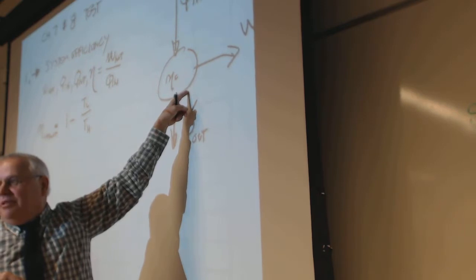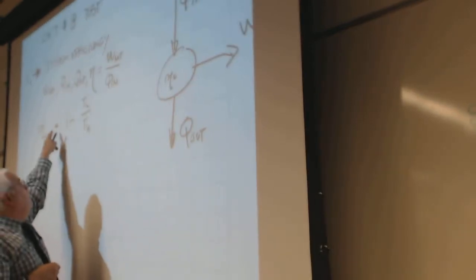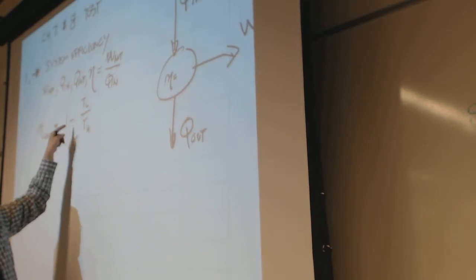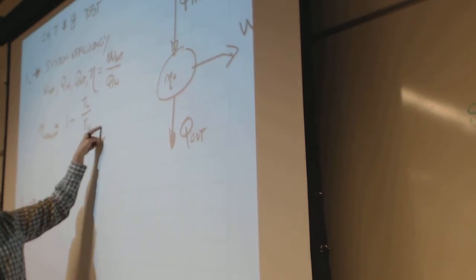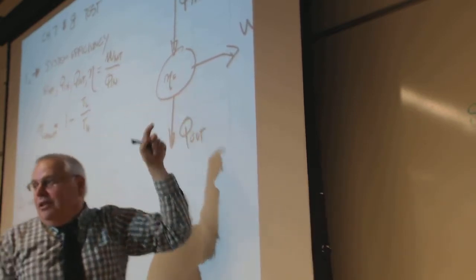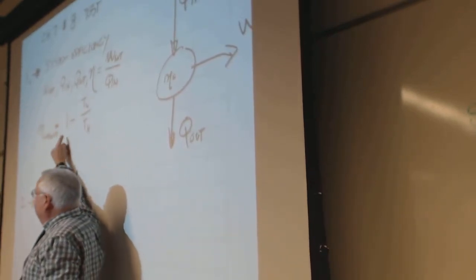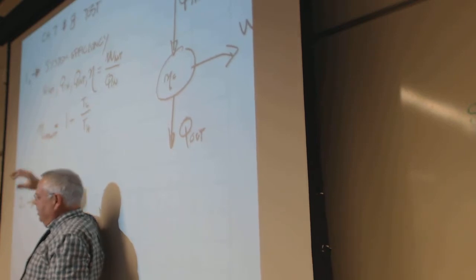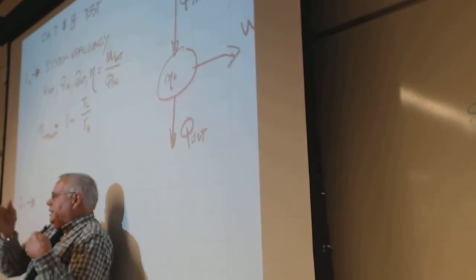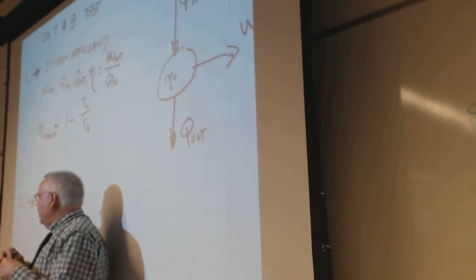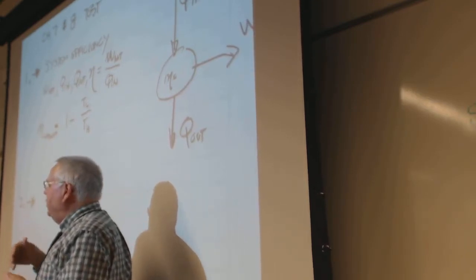So this was 25% efficient. If this was 50% efficient, then if you had 50% mechanical efficiency, 0.5 times 0.5 gives you 0.25. There's a chain in there. One of them is this isentropic efficiency, which is essentially what this is. And the other one is an efficiency: how efficient are you relative to that perfect one? And so that would be like including friction and stuff like that.